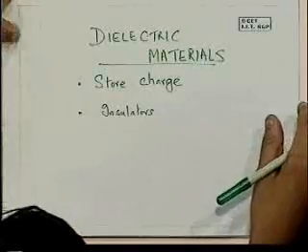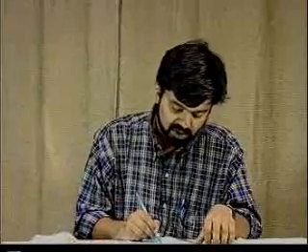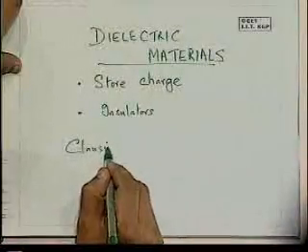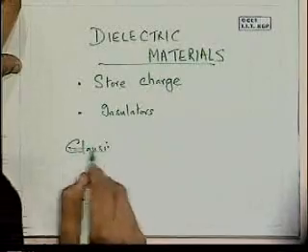And then we had looked at what are dielectric constants or relative permittivity, what is the different mechanisms. We had started considering one, the electronic polarization, and we had tried to relate the macroscopically observed phenomena of the relative permittivity or the dielectric constant epsilon r to the microscopic electronic polarizability through an equation that was called the Clausius-Mossotti. Did I get to Clausius? No, we didn't get there. Okay, we're going to come to it.